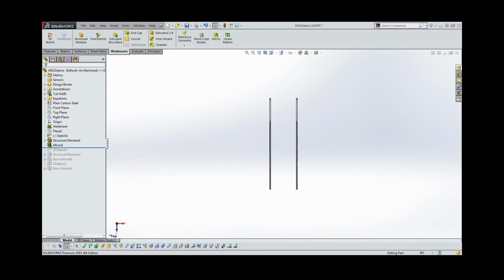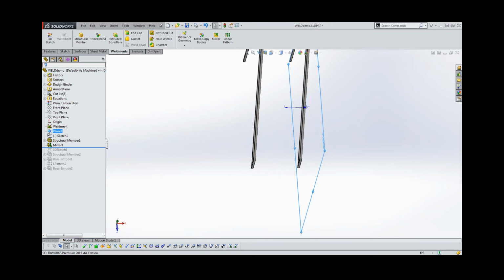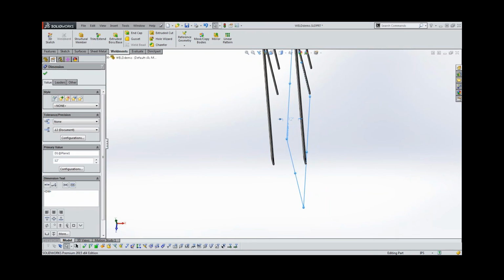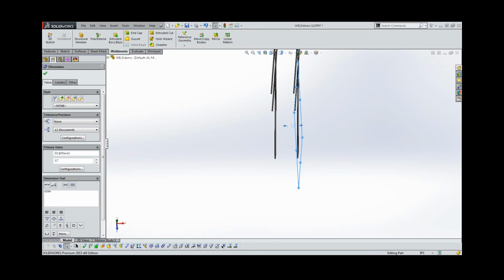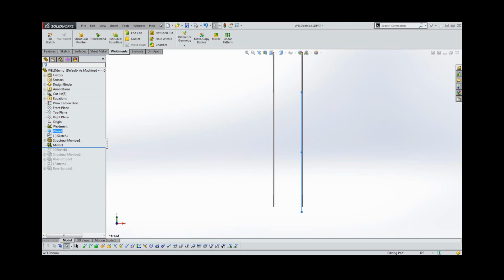And what we did there is, again, working from the constraints, they told us that the inside dimension on these had to be 24 inches. So we just offset that plane 12 inches for half that distance, and our structural member is to the outside of that plane. So we know we're going to be at 24 inches no matter what now on the inside of it.